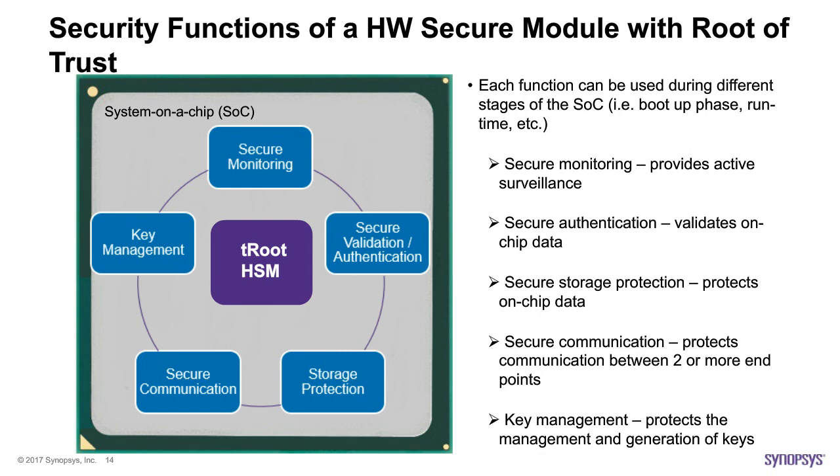Storage protection. As we mentioned earlier, this feature can provide a way to take plain text data in the SoC and securely encrypt it and authenticate it. The authentication and encryption can use a device unique key, so it can also uniquely bind it to the device as well. Secure communication. You can generate a secure channel between two endpoints.